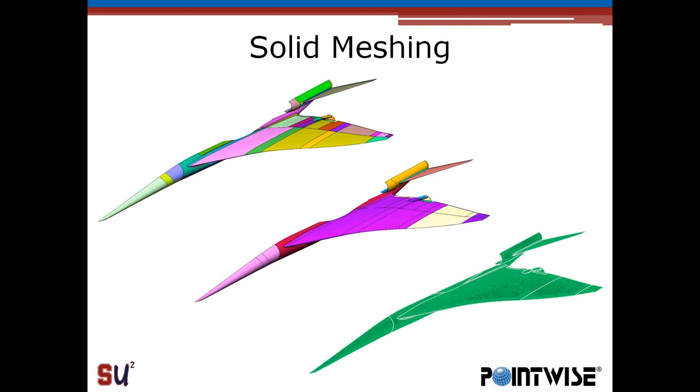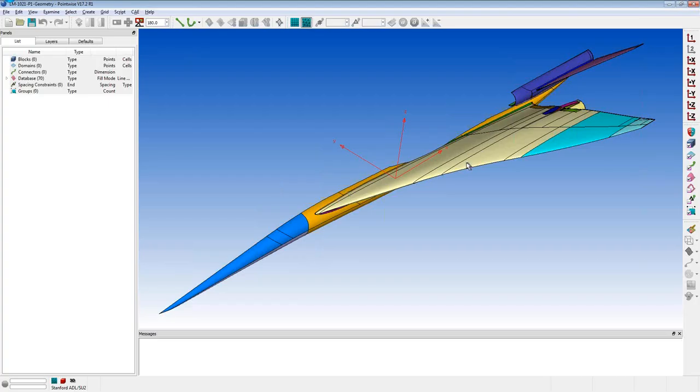And really what this allows you to do is structure up your mesh topology, your surface mesh topology, prior to even putting the surface mesh on the aircraft. We're not going to talk too much about this because we've discussed this in previous webinars, but this is the point at which we'll be starting with the watertight model, all quilted up, ready to go. And at that point, we can simply grab that model and automatically put a watertight surface mesh on it. So enough with this slide. Why don't I jump into Pointwise and demonstrate that?